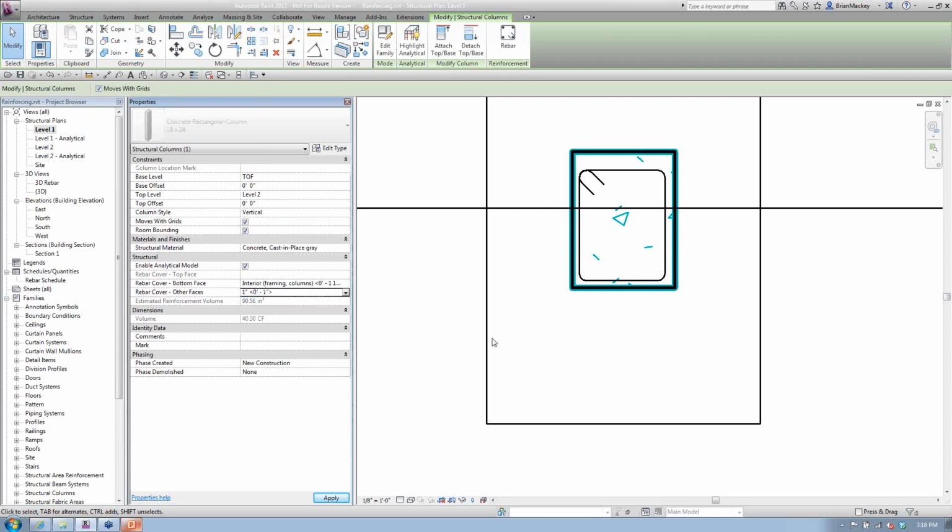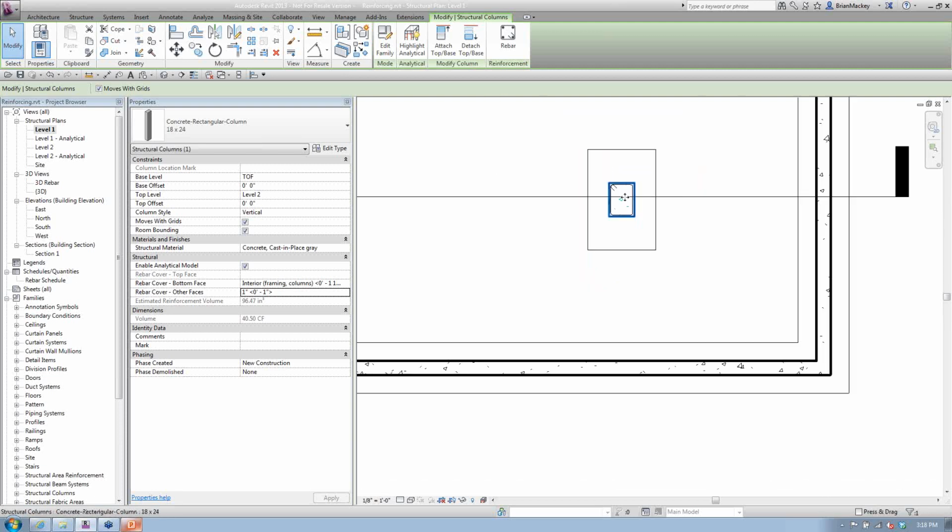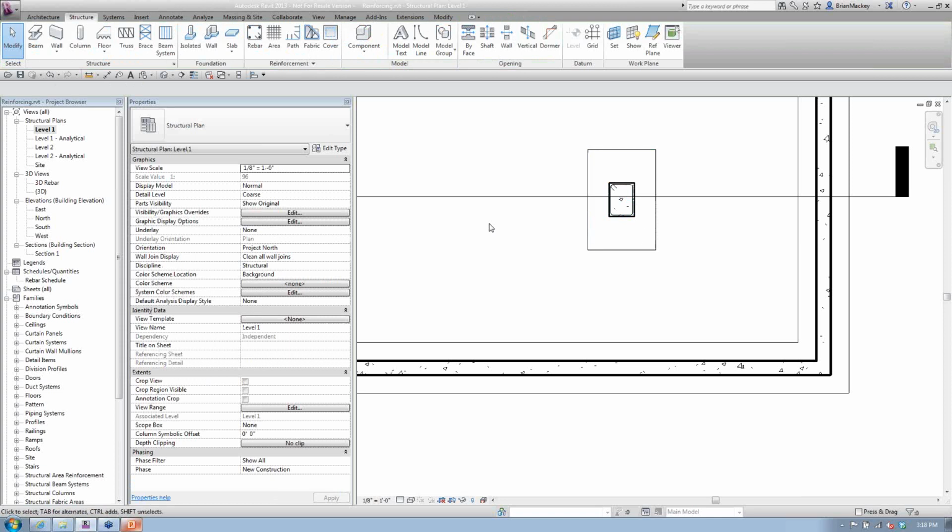Again, if you go back and change it, then you're breaking that for the individual faces you've changed and putting it in for all faces. Those cover settings are true for everything. Walls, floors, columns, beams. Those cover settings are going to be there for everything, and that's what's going to be your settings to go through and adjust those.